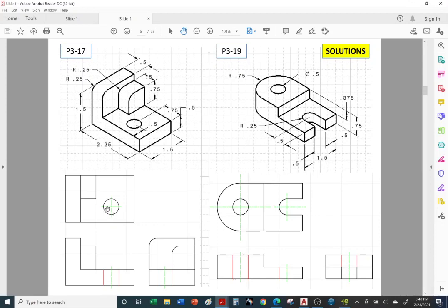So we use these imaginary green center lines. And also this hole, you can see is represented by the hidden lines. Okay, so when we're standing here on the side, we cannot see this hole. So we represent it with dashed lines, hidden lines, and I chose red for the hidden lines. See how it lines up? And also from the center, we're going to draw an axis.